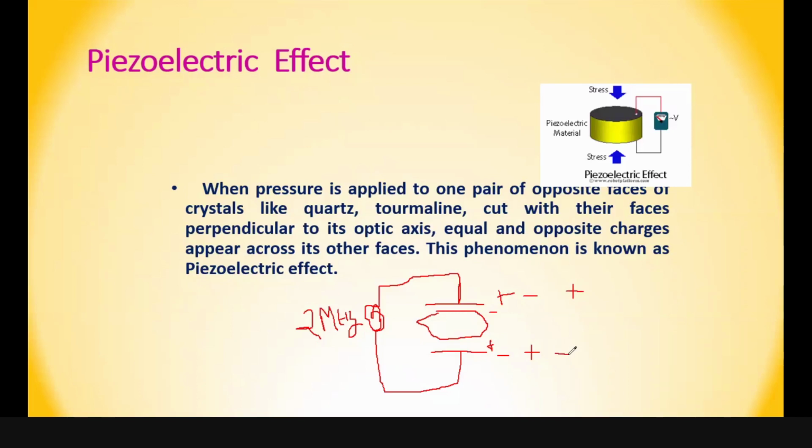Due to this, the charge carriers inside the crystal start vibrating; they start jumping, and due to this the crystal starts vibrating. There will be lattice vibrations. They will not be large enough to see with your eye, but they are known as lattice vibrations, right? So the lattice vibration vibrates the crystal. When the frequency of vibration of the crystal is equal to the applied frequency, 2 megahertz, because that is the frequency we have applied. You can change the frequency with the help of the oscillator, right?